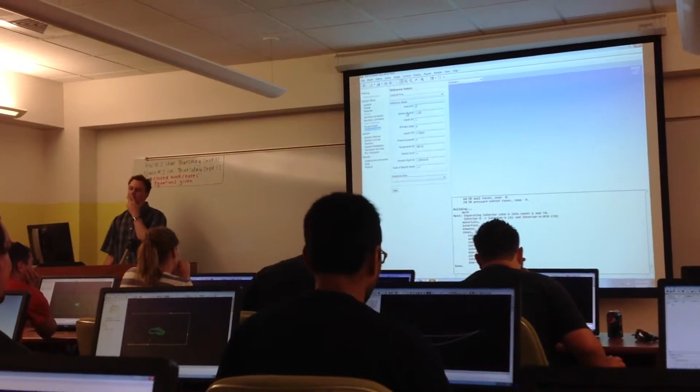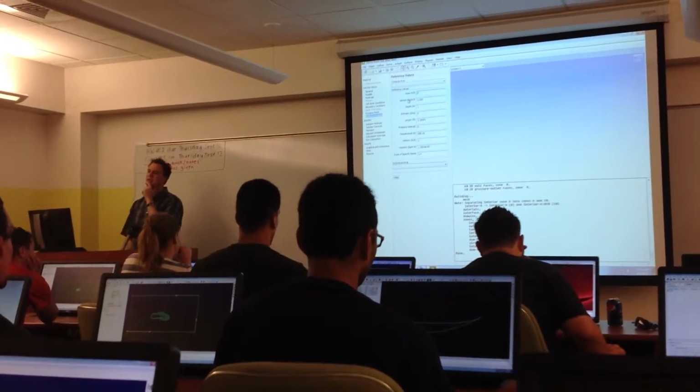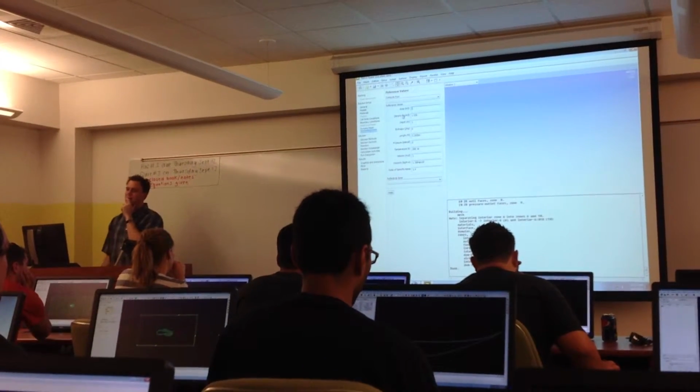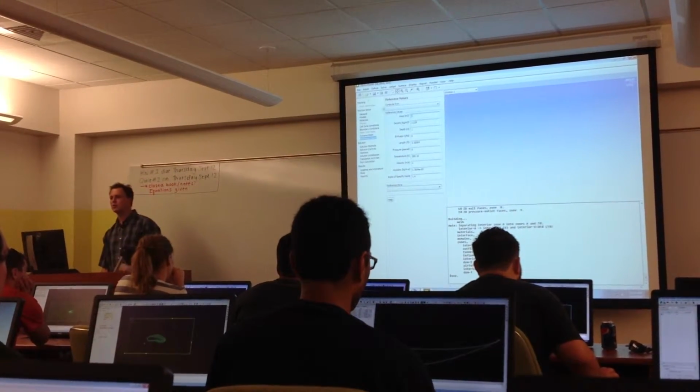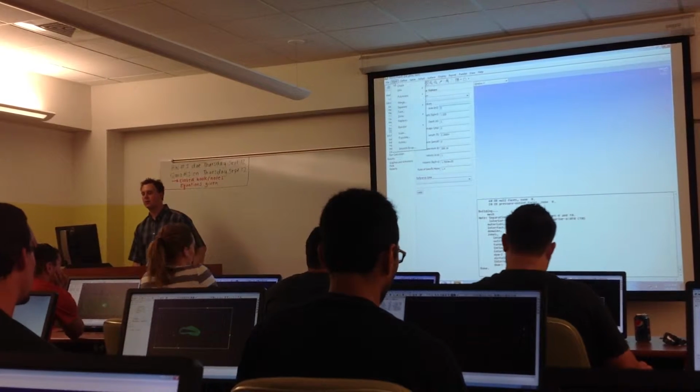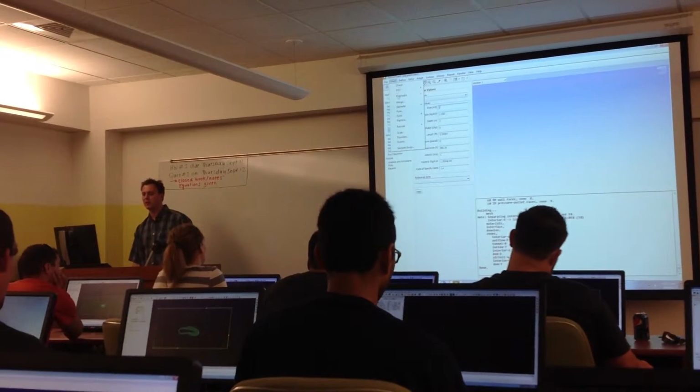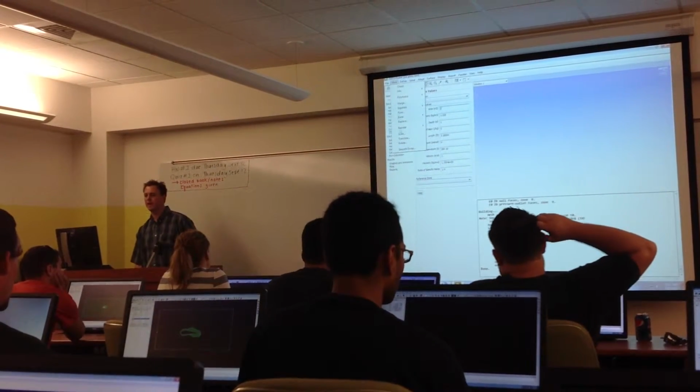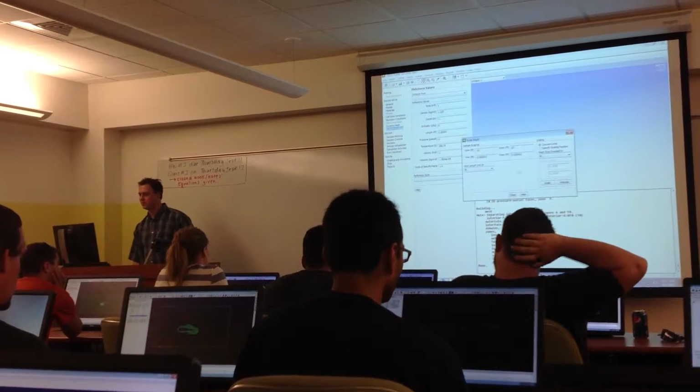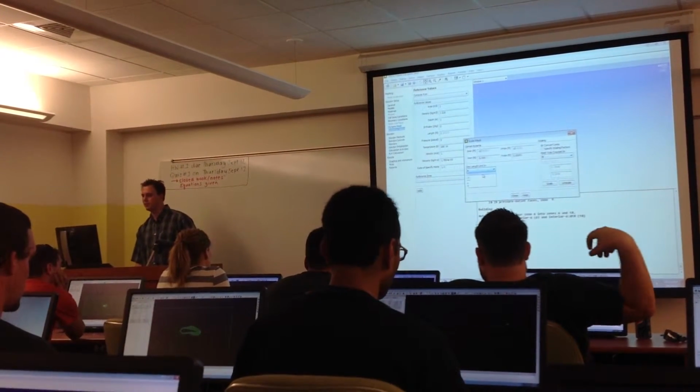I think the problem is Fluent does all of its calculations in SI units, and the safest thing would be to do everything in standard SI units. So let's go. We can fix that. I should have changed this. First of all, view length in meters.